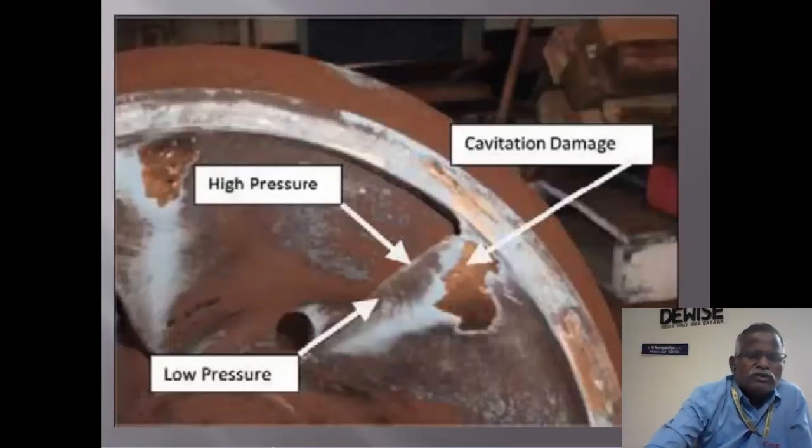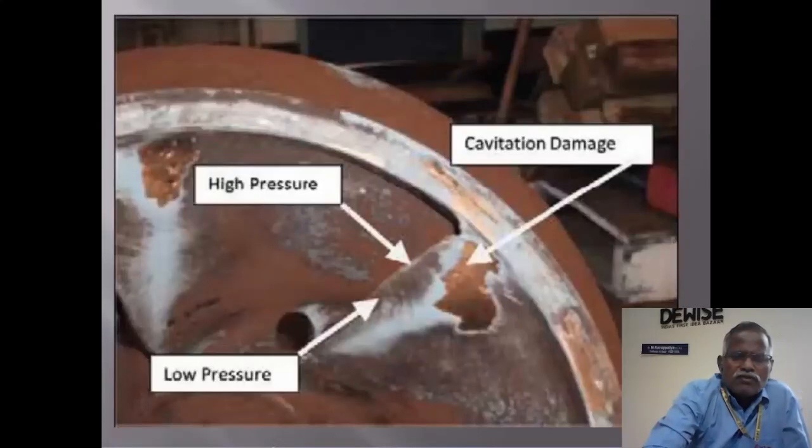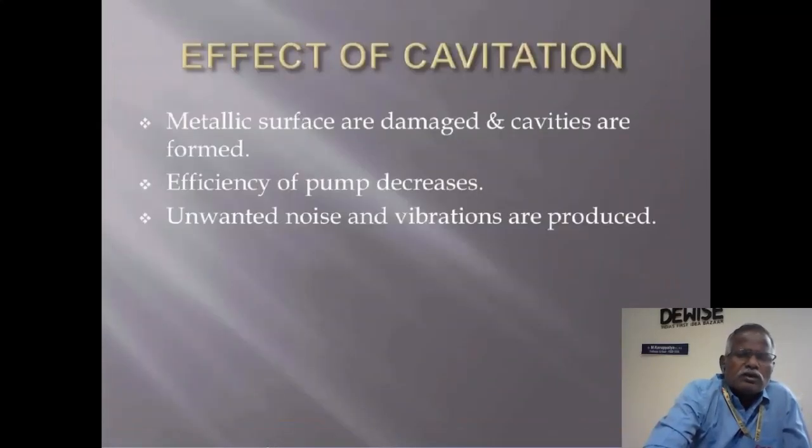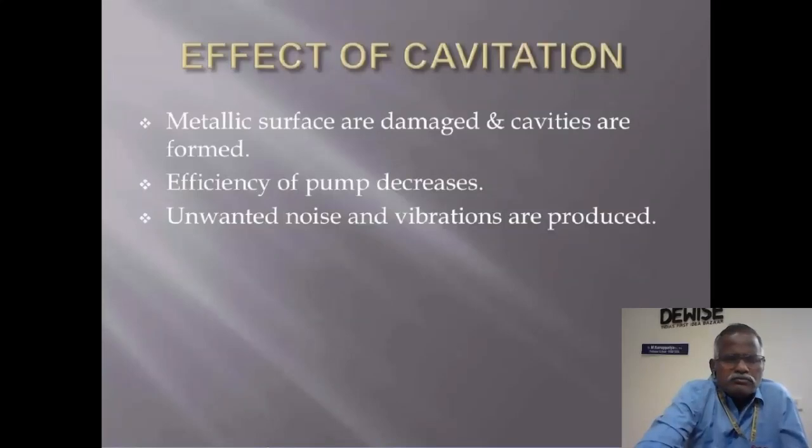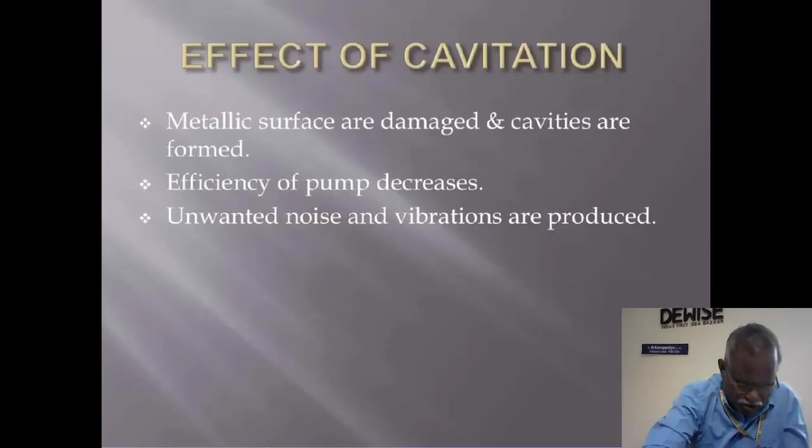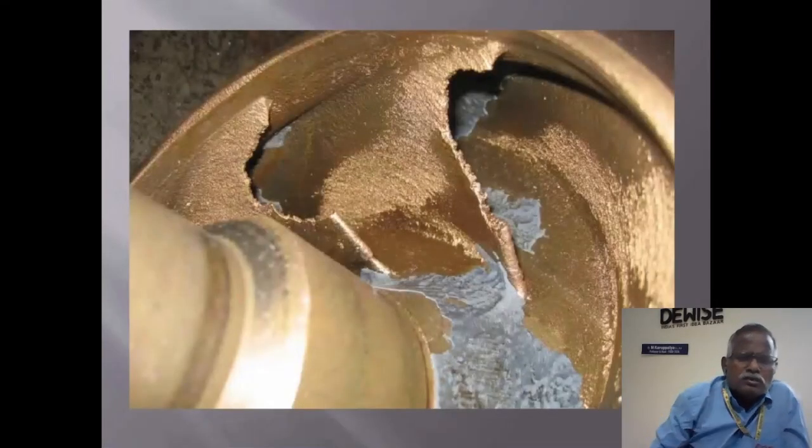We have low pressure, high pressure, cavitation damages. The effects of cavitation: metallic surfaces are damaged, cavities are formed, the efficiency of the pump decreases, and unwanted noise and vibrations are produced during cavitation.